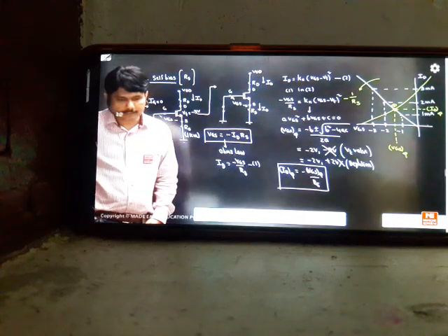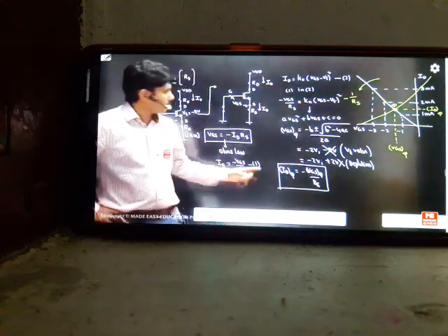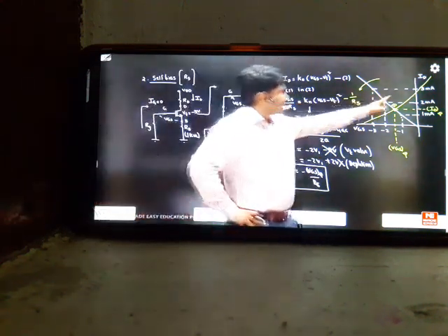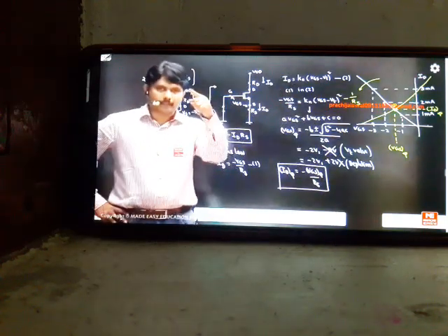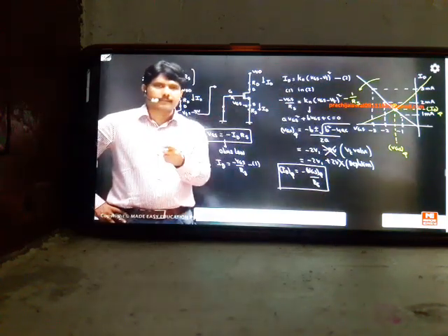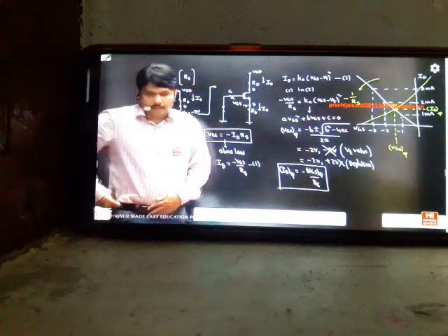After the linear line, the second line, how have you taken it? Alright, this is your line coming from the circuit. You designed a line from the circuit. But what is this other line? This is called the transfer characteristics experimental graph. You are doing some experiment in the lab and you are getting some graph for that. The graph is called the experimental graph, called transfer characteristics. Your load line is coming from your circuit. Both are intersecting at one point. That is called the Q point.